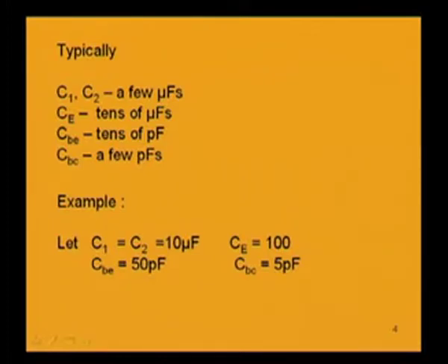With this concrete example, let us see the effect of the frequency of the applied signal on the reactances offered by these capacitances. For example, we will take C1 and C2 as 10 microfarad, CE as 100 microfarad, CBE in the picofarad range, say 50 picofarad, and CBC as 5 picofarad.